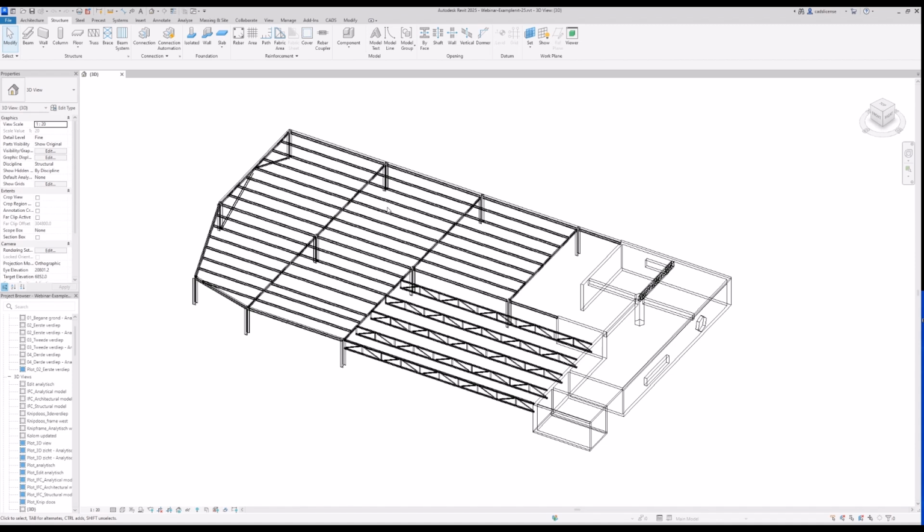Since Revit version 2023, it is possible to export this structural model. We still advise you to create an analytical model in Revit, since that analytical model will be able to connect each member in the nodes. With the structural model, it can still be possible that you will need to connect the members properly in SCIA Engineer afterwards.